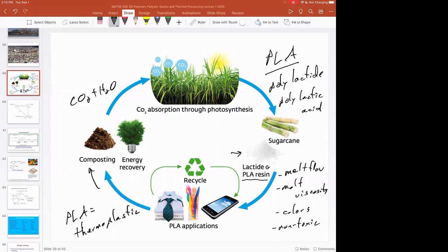If you have the choice between using PLA and polyethylene, you're mostly always going to choose polyethylene because polyethylene is about 10 to 20 times cheaper. And polyethylene is also tougher, which means it can take impact and other things like that. PLA is a little bit brittle, and making brittle consumer goods winds up making lots of broken plastic parts.